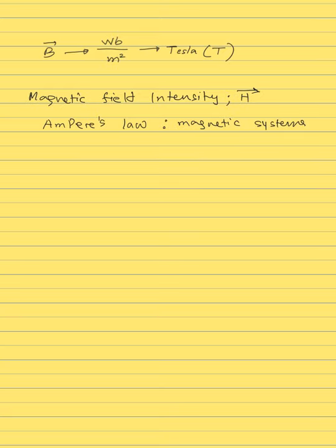and the Ampere's law. So magnetic fields that are produced by the current flowing in the coils, and the magnetic field intensity H that is determined by the currents and the configuration of the coils. So the flux density B depends on H and the properties of the material filling the space around the coil. And how the two are related, so B equals mu times H. This is called mu. So both of them are vector quantities, B and H.